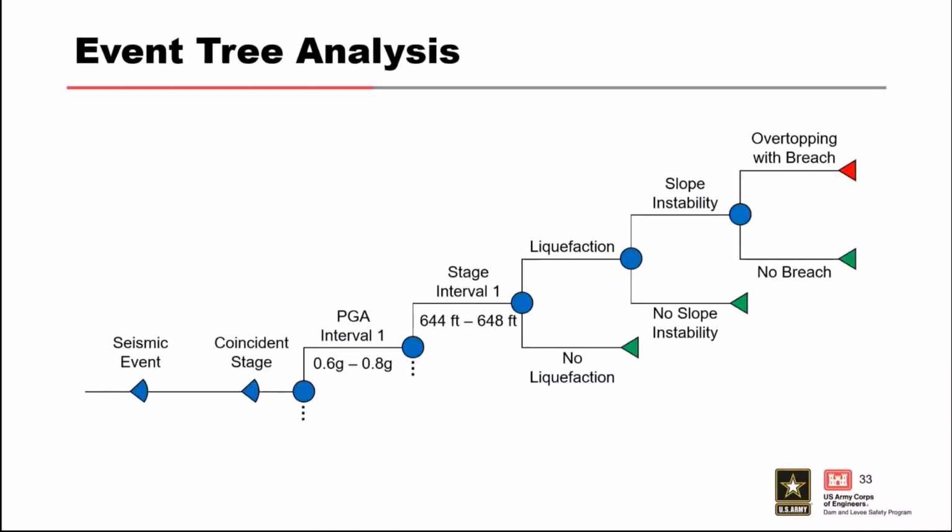Now, we said before, construction is sequential from left to right, beginning with the initiating event, proceeding with all necessary subsequent events in the order that they occur. The event tree doesn't need to be in chronological order from a mathematical standpoint, but a chronological construction improves the logic, which can facilitate understanding and communication of the potential failure mode. So it's usually a good idea to construct the event tree in chronological order from left to right.